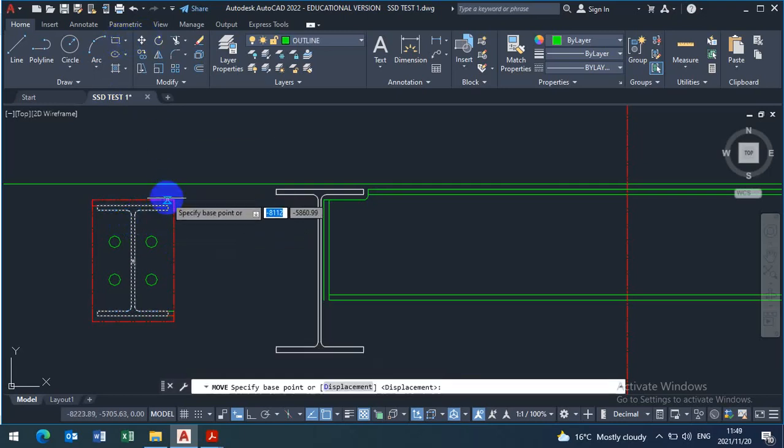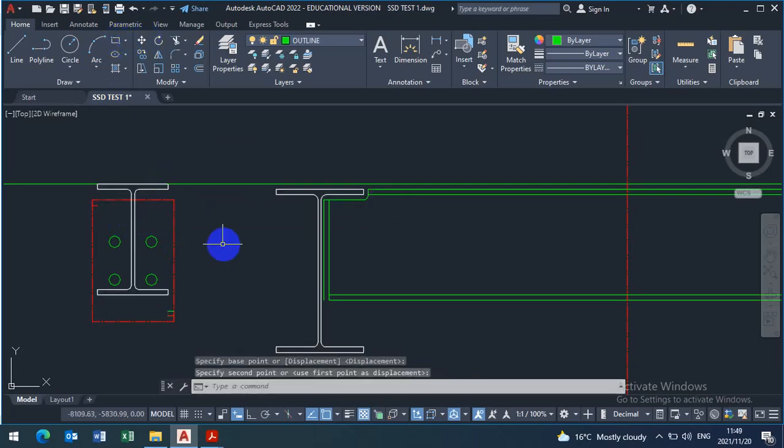Remember that your beam is in line up here. So once you put the plate there, you have to work with the pitch. From here you can offset or use the center of the plate, and this plate is too big. Make sure that it just can go all the way up to here, or even less. You offset 10 down here. That's how we do it.